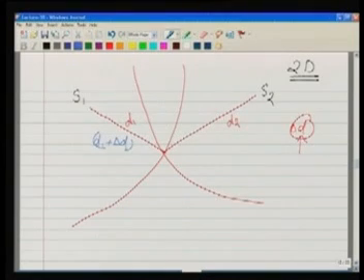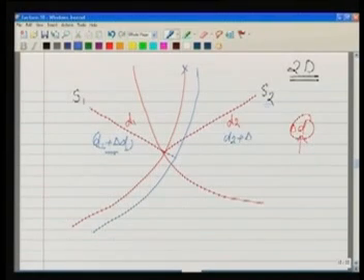Let us say delta d is positive, that means we should be somewhere along this circle, not on the earlier one, because we are measuring a distance which is d1 plus delta d. From the second satellite also, we will be measuring d2 plus delta d. That means we should be somewhere along this circle from S2.